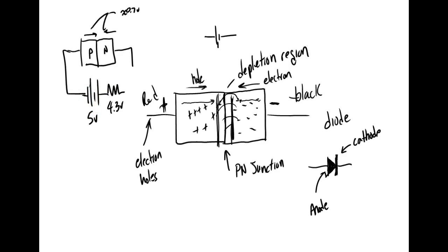What's going to happen? So here's an N, here's a positive. This is going to start sucking electrons out this way. It's going to make the barrier voltage bigger. This is going to come over here and start sucking the holes out and make this barrier bigger. And after a time that we can't even understand, there's no path anywhere for anything to flow. So the thing stops. You understand that?